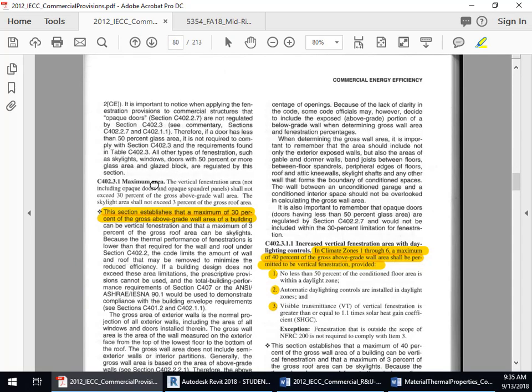You'll notice that the maximum area for fenestrations, that's glazed area including glazed doors, is 30%. Okay, that is set by code. If the municipality that you're working in says 30%, they're following the IECC code. Now, you can get around that 30% if you show them performance data that says the building performs better if we have 40, 50, 60%.